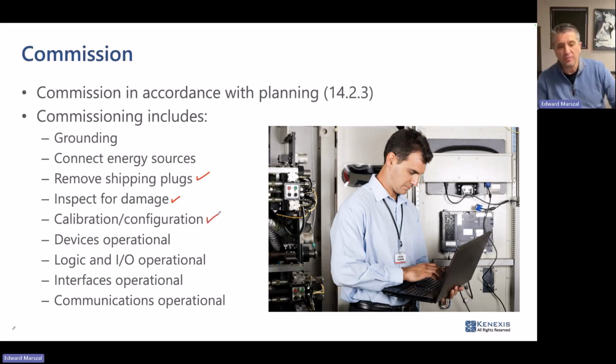Next thing you need to do is a calibration or a configuration. Now, back when I was at UOP, I wasn't doing this. I was basically only doing the preliminary checkout, and the site's electricians and instrument technicians would be doing this stuff. So we're going to connect calibration tools to the devices, hand pumps, calibrated pressure gauges, and so on, and set the 0, 50%, and 100% of span for a 3-point calibration, or a 4 or 5-point calibration, whatever your company standard is for doing the calibration.